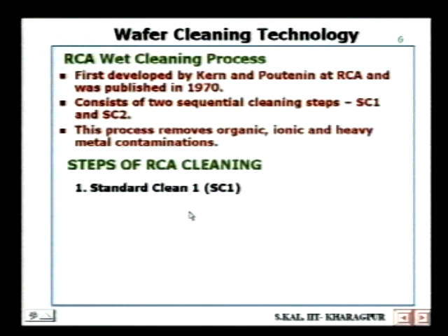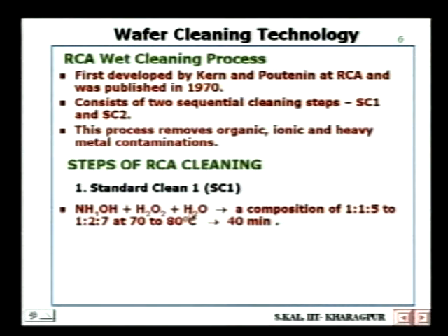The first step is standard clean 1, SC1. The SC1 solution is NH4OH, H2O2 and H2O: ammonium hydroxide, H2O2 is hydrogen peroxide, and H2O is water, obviously deionized water.